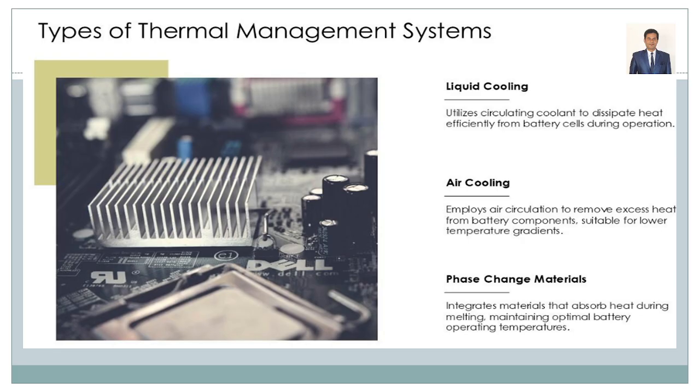So that's why even in most electronic boards we have power semiconductors or power electronic devices which deliver a lot of heat. That heat will be trapped by the heat sink, right? In this diagram, there is a heat sink, isn't it? So like that, it will trap the heat, absorb it, and give it to the external environment. Like that we also have to have certain types of cooling system, right? It may be liquid cooling, air cooling, or phase change material. So these are the different coolings you have to adopt for your thermal management system in the BMS.